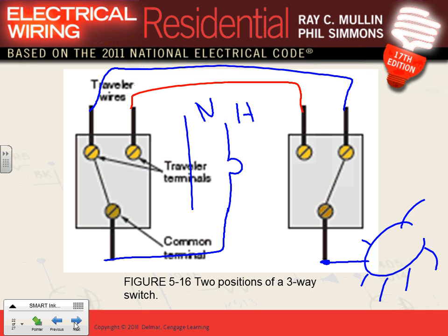And I'm not wiring them with, okay? So what am I missing now? In order for the light to work, remember, unless you tie this other end to the ground, like Shad would do in his basement, not efficient, not safe, then you have to pull the neutral. So what do you need to do? Then you take your neutral here, and you're going to grab it and feed it to this fixture. That's basically a simple wiring of a three-way switch.